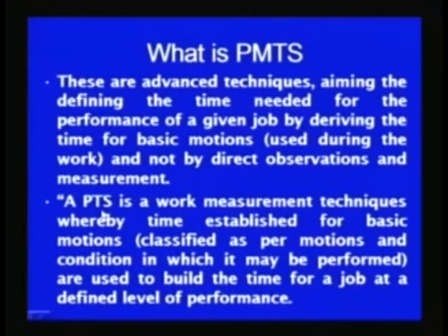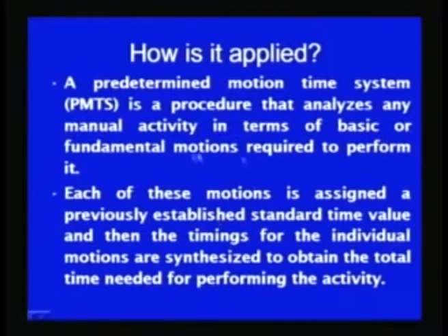The PTS is defined as a work measurement technique whereby the time established for basic motions is used to build up the time required for a job at a defined level of performance. These basic motions have been defined and categorized in different ways in the different PTS systems which have been developed.